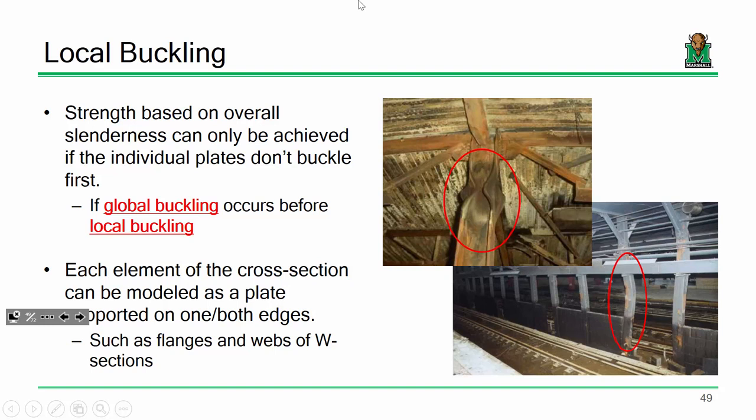Because if you come out and you design a bridge, you've at least heard of this stuff. In this course where you're designing bridges and you're specifying plates and web thicknesses and what have you, you are the one who is actually tailoring the size of this girder. So in buildings and using a rolled shape, not really a big deal. In here, it's a really big deal, okay? Because it's very possible that you size a girder that's controlled by local buckling.